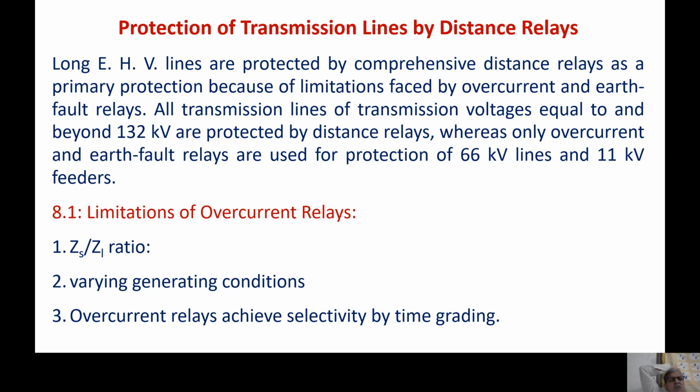So if fault current with minimum generation is less than load current with maximum generation, then it is difficult to set the overcurrent relay alone. You have to use the voltage controlled overcurrent relay, and principally the voltage controlled overcurrent relay is the principle of distance protection. So we have come to distance protection in that case, as the remedy.